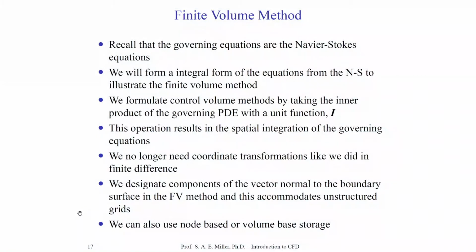There's two types of finite volume methods. There's node-based and volume-based storage. A node-based scheme stores values at each nodal point within the computational domain. A volume-based storage scheme uses the volume centers. That stores the fluid dynamic solution at the center of each volume. The solvers are typically written either way, and there's advantages and disadvantages to both approaches. Perhaps the biggest advantage of the volumetric approach, of course, is that it will store the solutions at the middle of the volumes and have less memory requirements, but you'll have less knowledge of the solution because you only know the solution at each particular volumetric center.